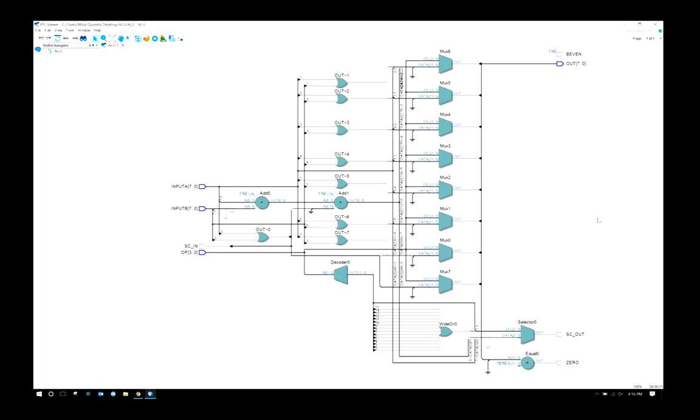So what it is, it's just showing you in a reg file you have a bunch of muxes, you have some gates, all that stuff. You don't need to worry about the implementation of how to make it gate level. This is just, we want to see that the code you wrote for your module was synthesizable. So this shows us that your code can actually be made into hardware.